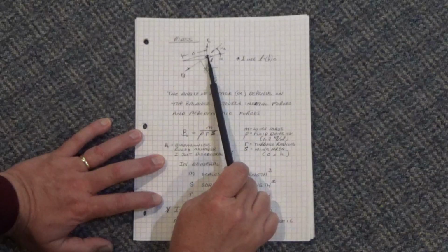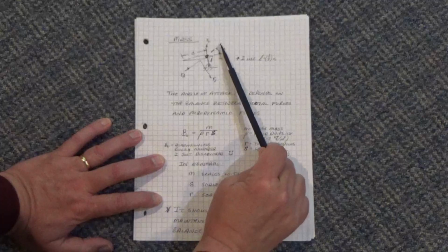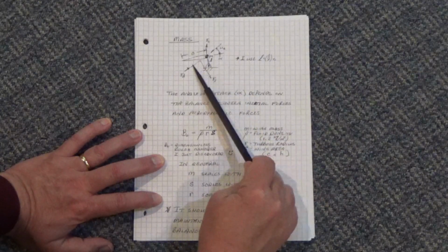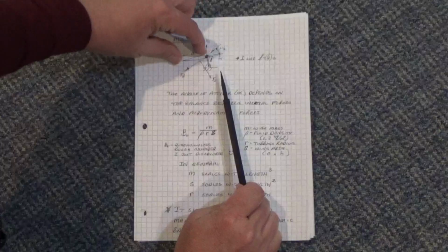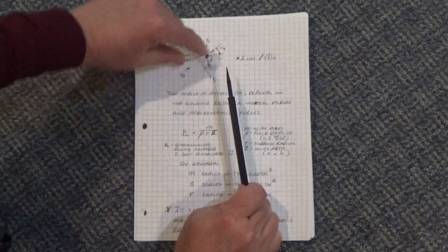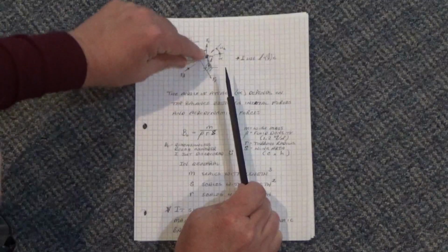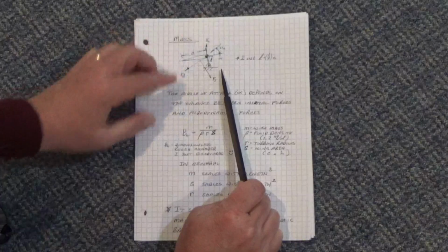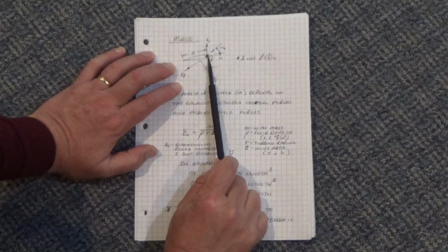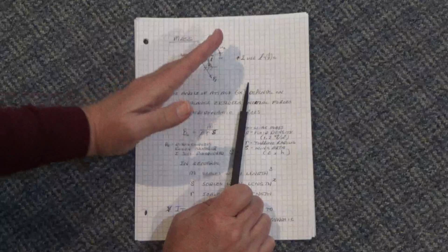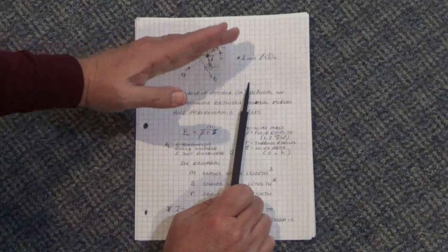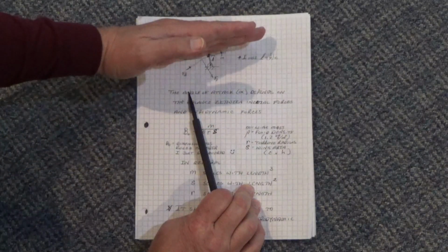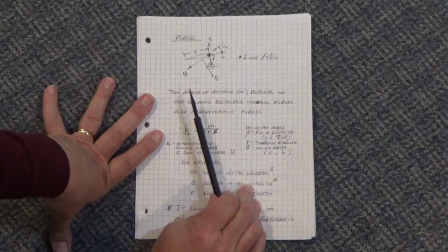So here's the wing on the pivot, and what happens in the Sharp VAWT is you have this angle of attack. The wind is coming at an angle, so you get drag, and that tends to want to rock this backwards. You have lift that also wants to rock it backwards so that it weather vanes, so that the wing will align itself with the incoming wind. However, there's a pendulum here with the mass pulling outward on it, so it tends to pull it back a certain amount, and that develops an angle of attack, which creates lift and drives the turbine forward.